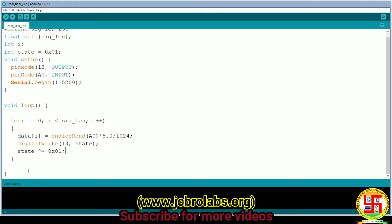Okay, so let's check. I hope everything is fine. Right now we are not sending the data to the computer, because otherwise we will have some problem while reading the sampling rate. So right now it is simply reading the data and then toggling pin number 13. Toggling takes a very small fraction of time, because our Arduino is running at 16 megahertz and it just consumes one clock cycle. So it will not have much effect on our sampling rate.